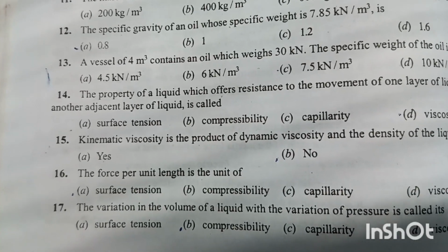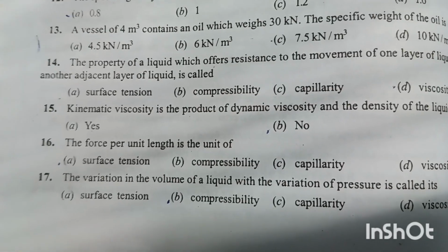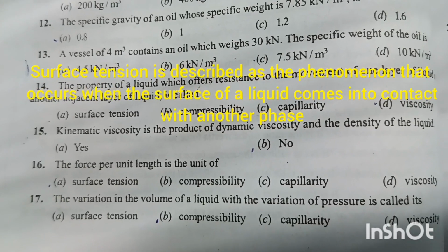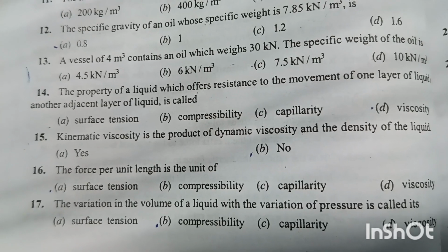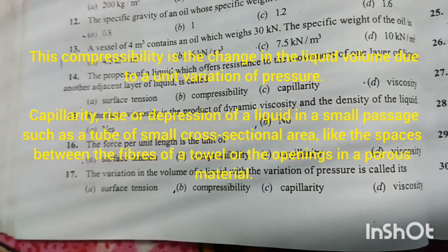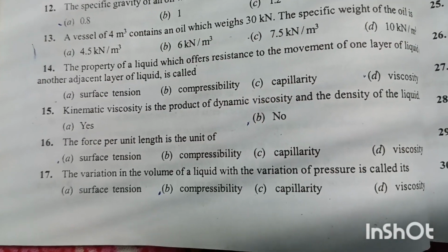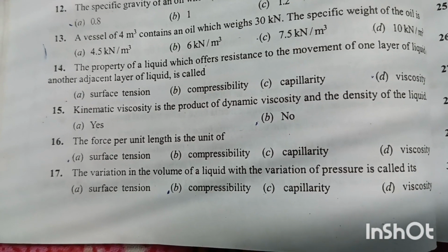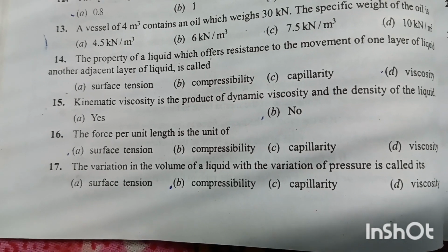Question number 16. The force per unit length is unit of surface tension. Option A is right answer. And the surface tension is a tendency of a liquid surface at rest to shrink into minimum possible surface area, displayed by its acting as if it were a stretched elastic membrane. Compressibility: the change in volume of a liquid due to unit variation of pressure is called compressibility of the liquid. And capillarity: the phenomenon in which liquid spontaneously rises or falls in thin tubes or in the voids of a porous material is known as capillarity of liquid.